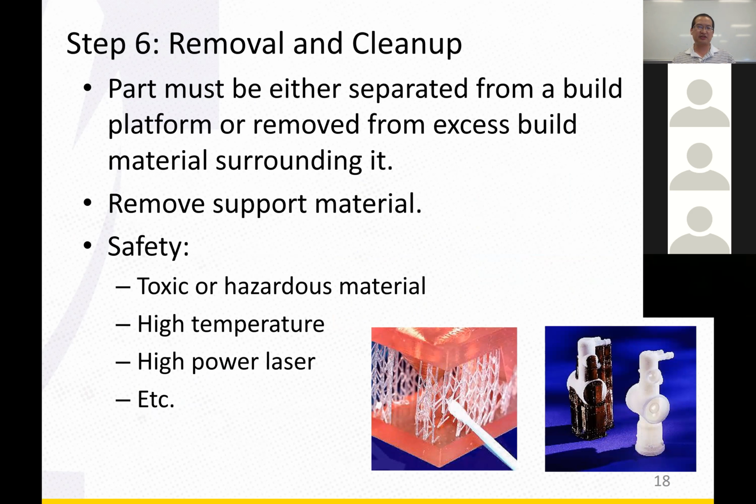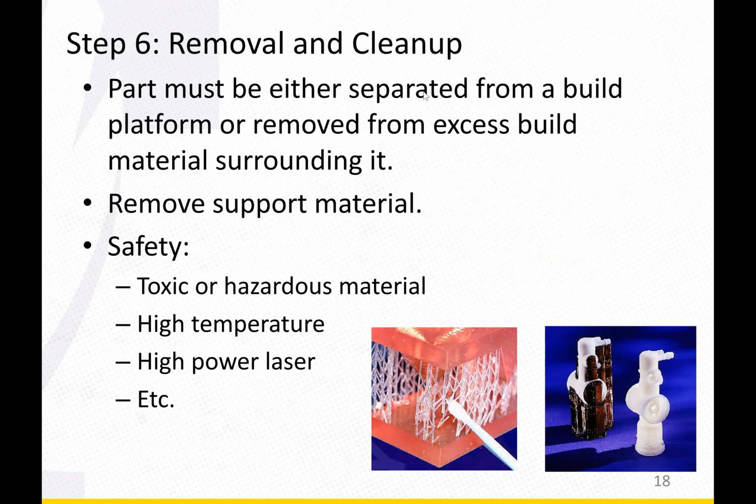Then step 6 is some post-processing, right? As I mentioned, you probably need to remove all the support material and also clean up the building material. For example, with some liquid-based methods like stereolithography, you need to wash the part you printed, and also remove the support material.